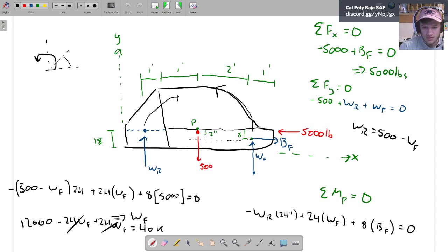So if I go back to my diagram here, this means that the force at this wheel, the force that the suspension's providing here, is actually pulling on the chassis. And in this scenario, that's probably a weird thing to think about. But the idea there is, you can think of it as the suspension acting as a spring, trying to rebound the chassis back towards it.